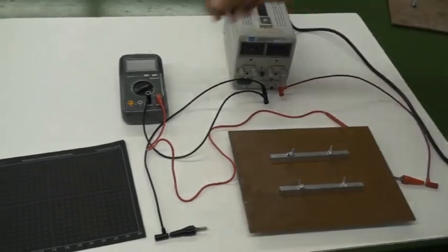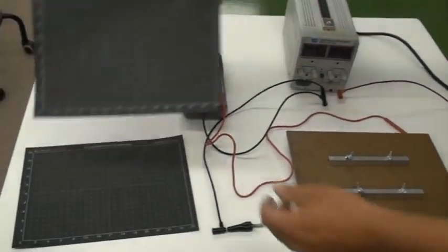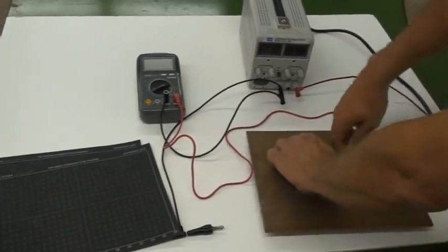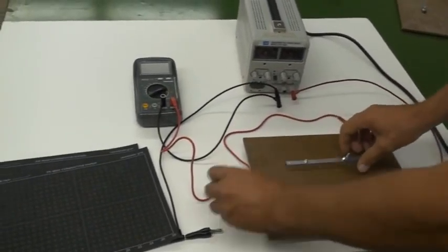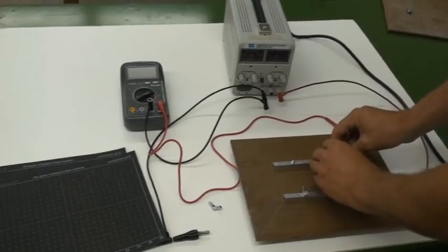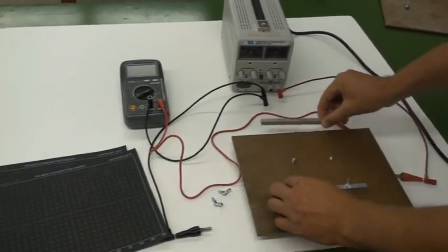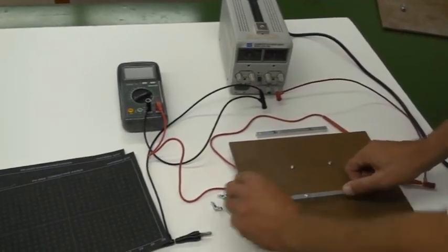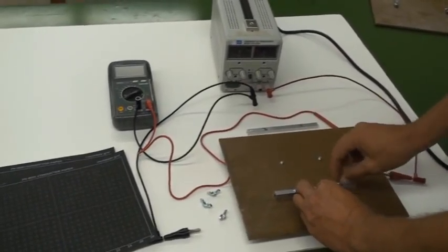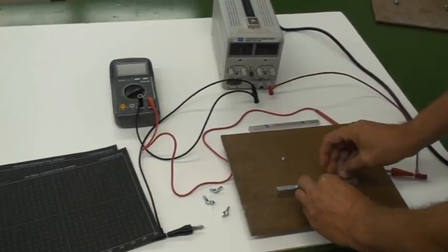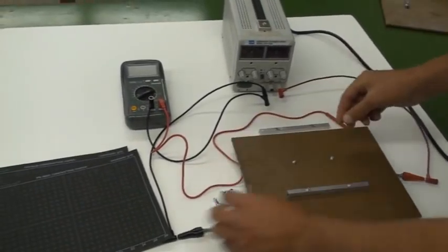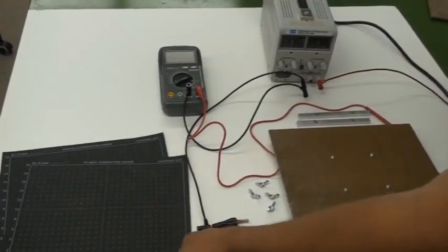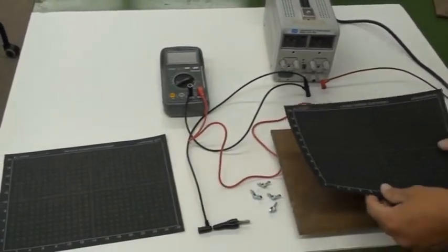The long straight conductors are placed parallel to each other and in contact with semiconducting paper. Plus 10 volts is attached to one of the conductors and 0 volts is attached to the other conductor. The conducting paper allows a trickle of current to flow through. If you're fortunate, your lab TA will have already put the semiconducting paper in place with the conducting bars. Otherwise, you'll need to carefully punch holes in the paper for the screws to pass through.